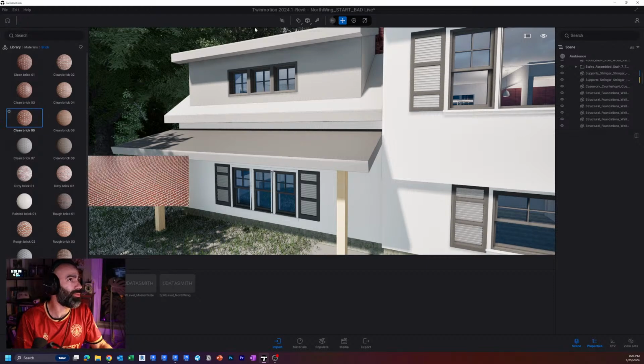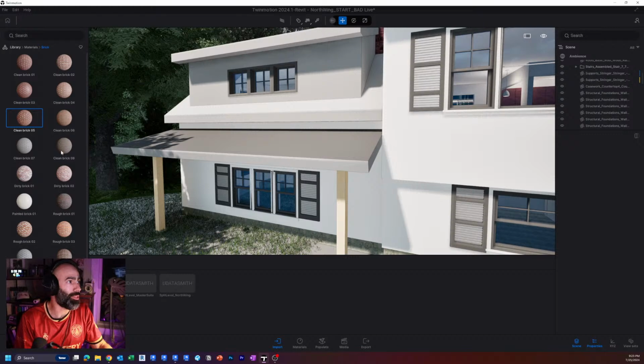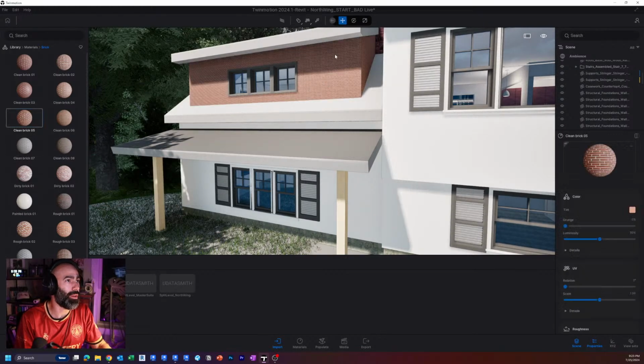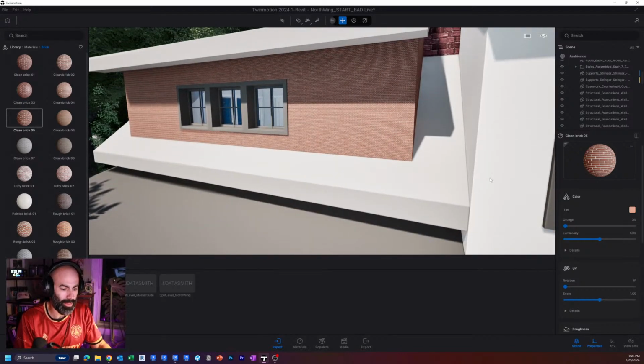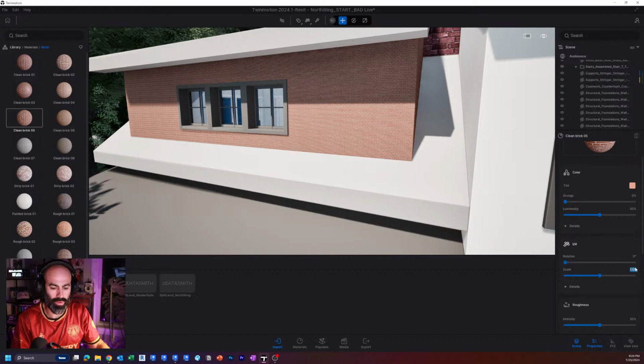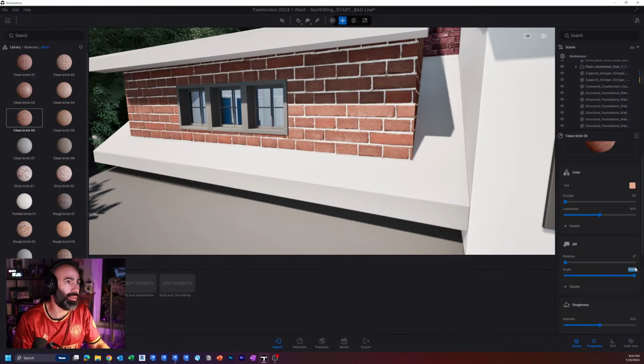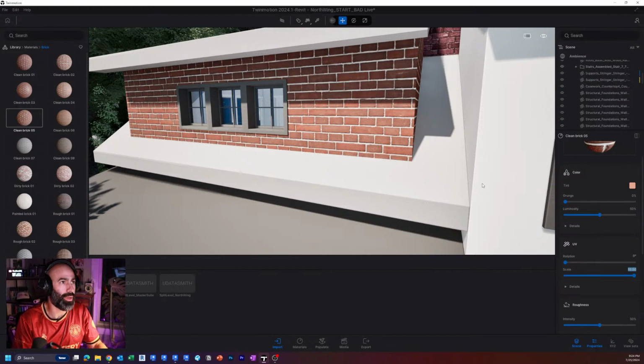So if I take this brick material, right? If I set this default to from object UV and I throw this brick on here, you'll notice the scale is tiny, right? And so what I've been doing forever until I figured this out was I go over here and I type 15 or 10 or whatever the hell it is to get it close, right?